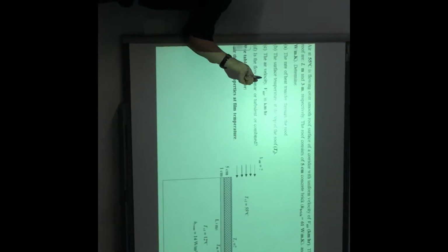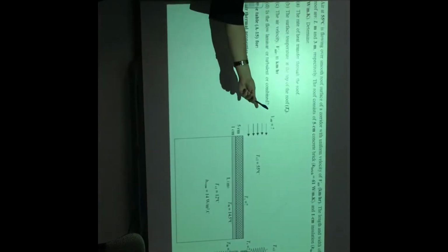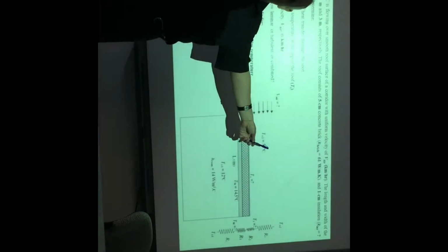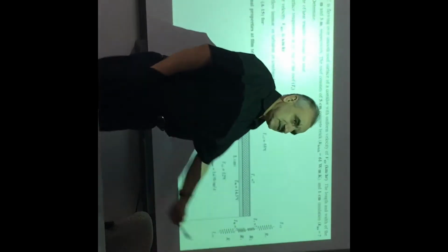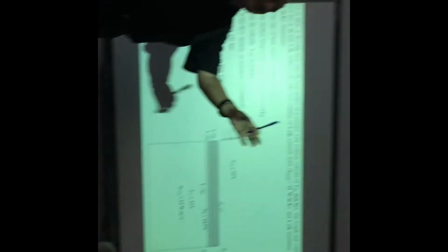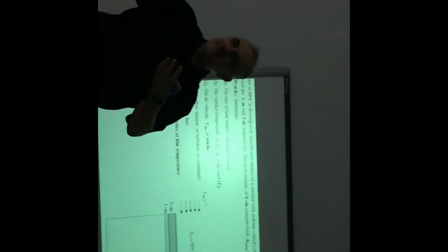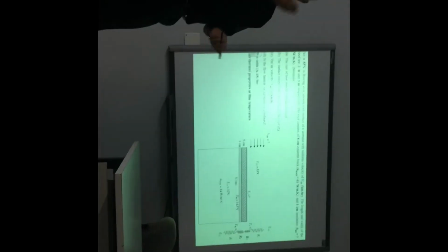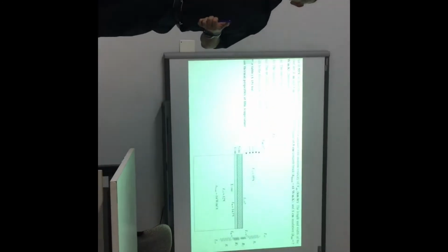So, as I said, this part is the hardest part. Go back, find first the Nusselt number from h outside, the convection outside, because h here is unknown, and h from the resistance. After you determine h, apply the equation of Nusselt number to calculate Reynolds. Now remember, you have an equation for laminar, an equation for turbulent, and an equation for laminar plus turbulent. So you say, okay, which equation should I use? Here you have to make an assumption. For instance, start by assuming laminar.